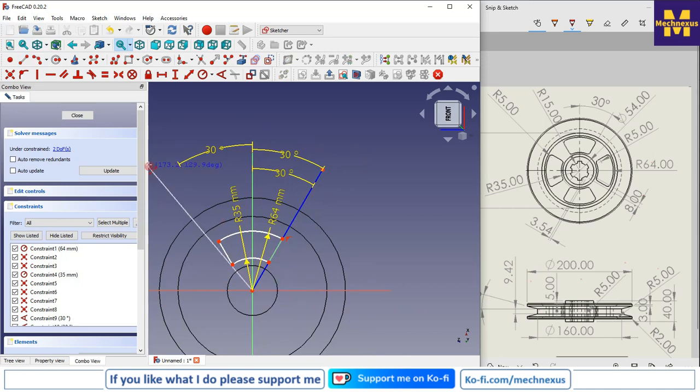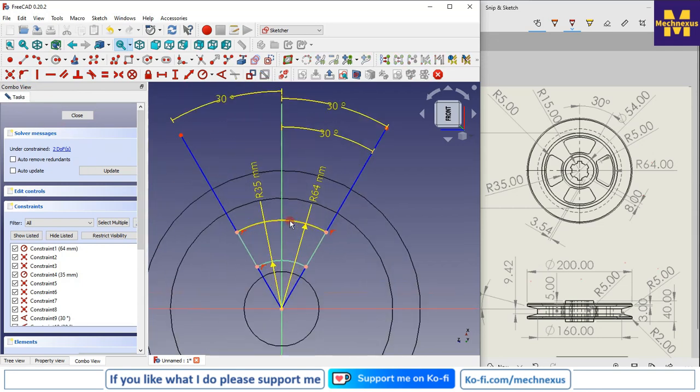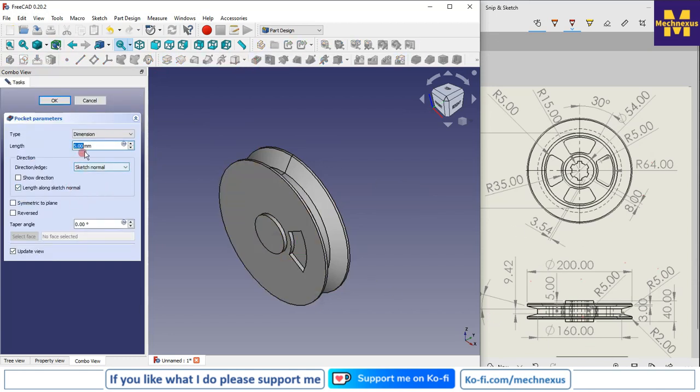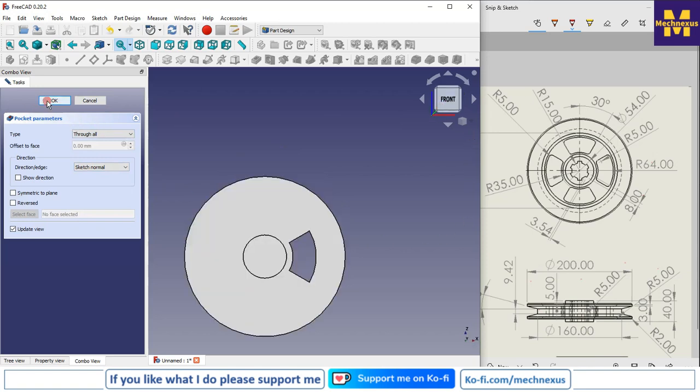Now same way I will draw the construction line on the other side, make it construction, and same way I will select this point and this line and make it a coincidence, and this one coincidence. So here our sketch is constrained, and now I will come out of the sketch and I will switch to the flat lines. Now I will go with the cut, and it is a through all cut, so I will select the through all and I will say OK.